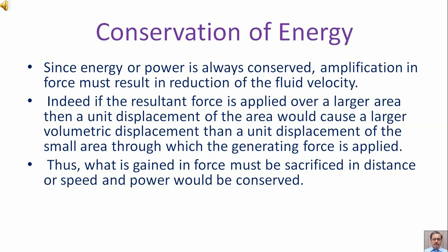Indeed, if the resultant force is applied over a larger area, then a unit displacement of the area would cause a larger volumetric displacement than a unit displacement of the small area through which the generating force is applied. Thus, what is gained in force must be sacrificed in distance or speed, and power would be conserved.